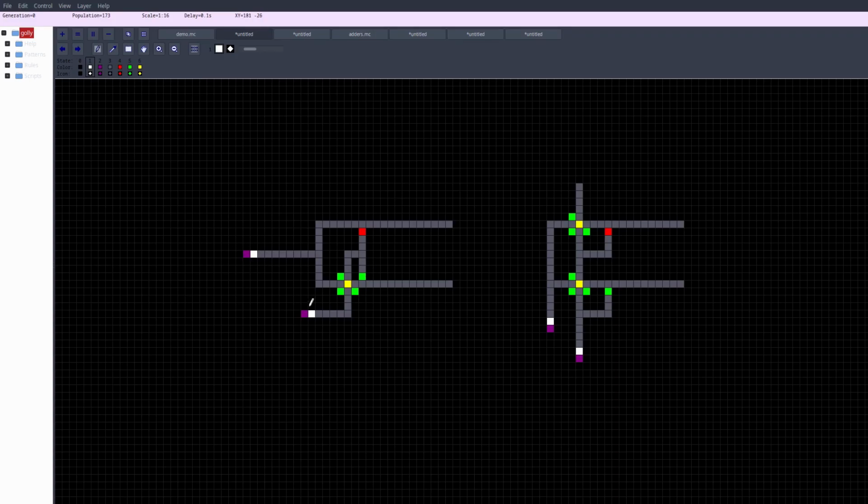This is the data input, and this is the selector. If the selector is 1, the data will go to the top output. If the selector is 0, the data will go to the bottom output. If the data is 0, no signal will appear at either output.